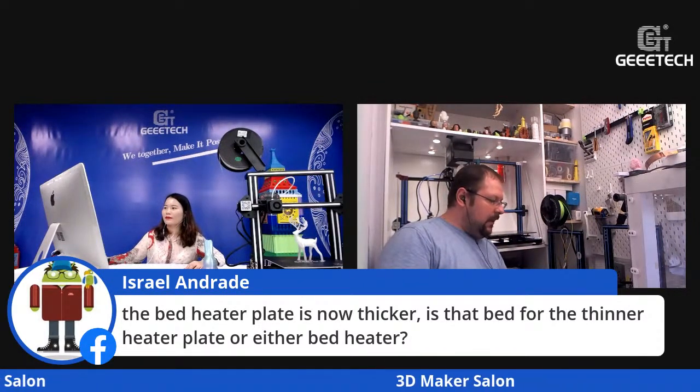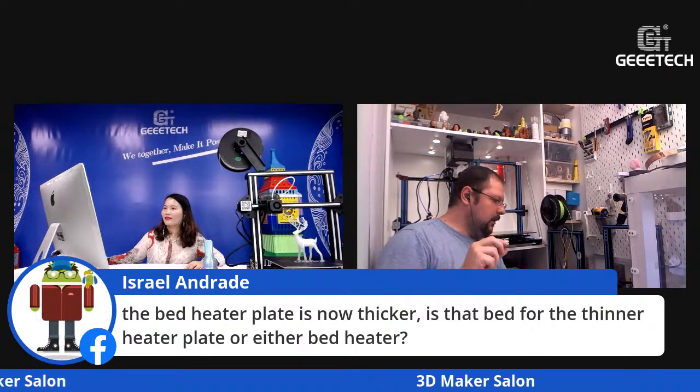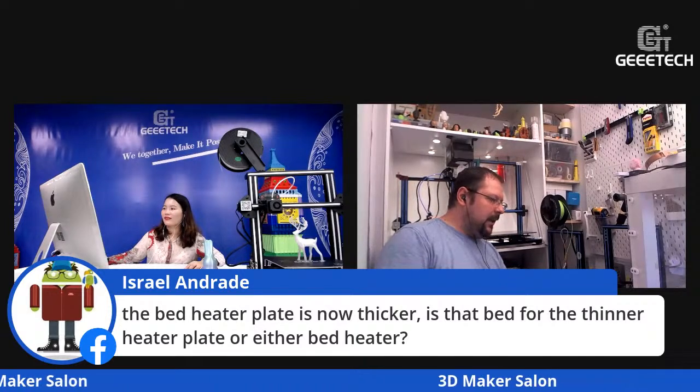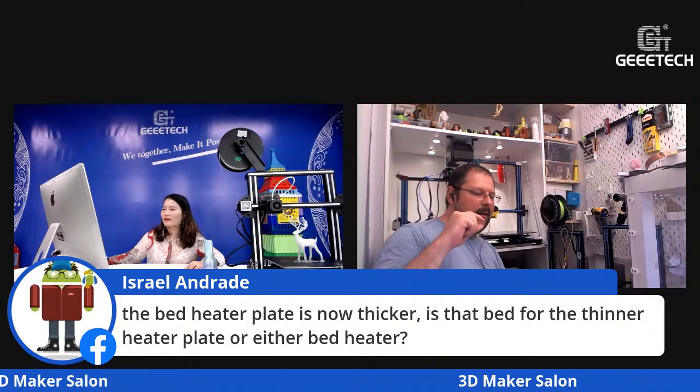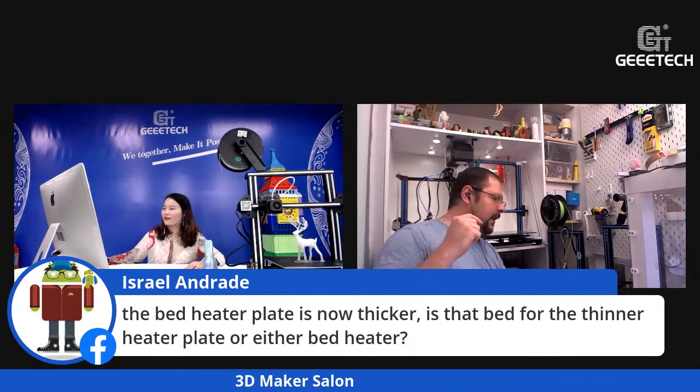No, because glass has other temperature properties than aluminum. The thicker aluminum plate will conduct the heat much better than a thinner glass plate. So if you exchange the glass plate for the cast aluminum plate, it will be as good or even better in heat conductivity, because aluminum conducts heat better than glass. So it's no problem if the aluminum sheet is a little thicker than the glass. You only need to re-level your bed, and you can print right away onto it. So it's not bad for the bed.